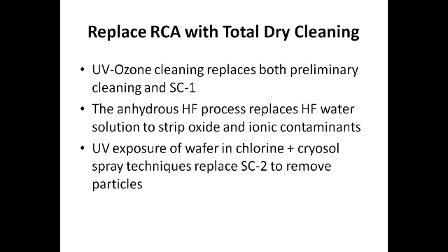I use 3 dry cleaning techniques, actually 4, to replace every step in RCA cleaning. UV ozone cleaning can replace two steps in RCA, preliminary cleaning and SC1. Anhydrous hydrogen fluoride can replace the hydrogen fluoride water solution.